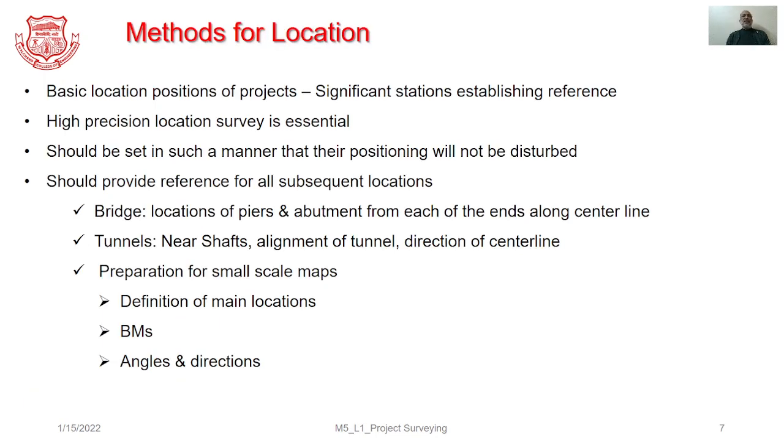There are certain methods for locations. So it is essential to define the basic locations related with that particular project. These would be some significant stations which will help us establish the reference for the further stages of the work. This work is highly precise in nature. It should be set in such a manner that their positions will not be disturbed. It should provide reference for all subsequent locations.